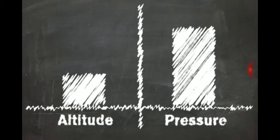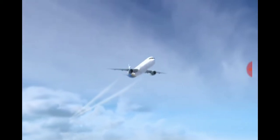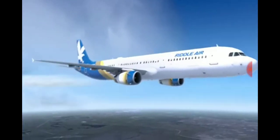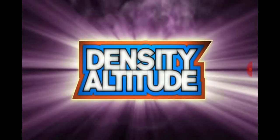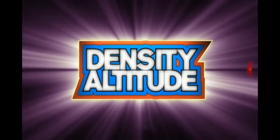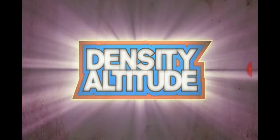Also, the pressure of the air goes down as altitude increases, so the higher you are flying, the lower the air pressure will be, and consequently, the lower the density will be. A better way for pilots to make sense of how density affects airplane performance is to use something called density altitude. Density altitude is a way of describing how the airplane will perform when put in context of an altitude.